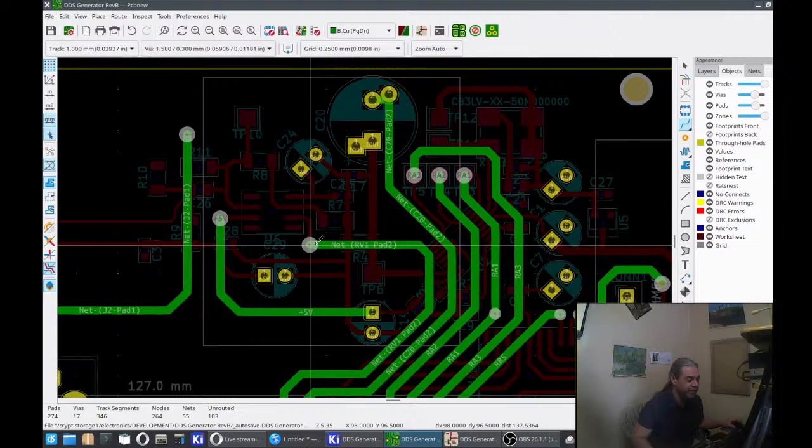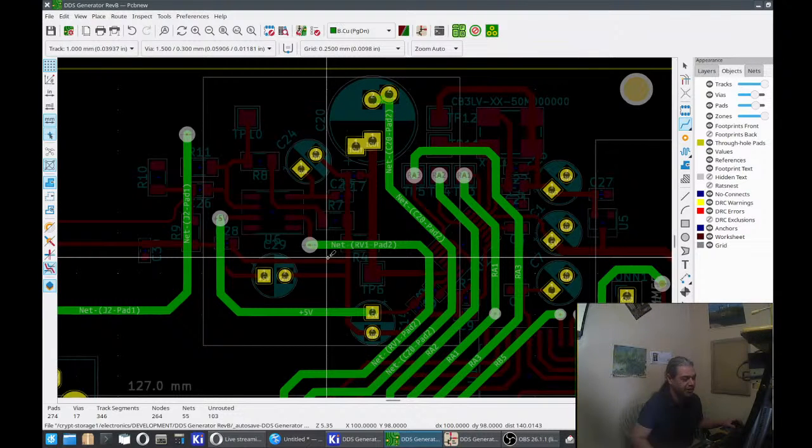So it's whatever you can have in stock, because with those capacitors, you shouldn't have to bend the leads and have the components not seated properly on the board. And by doing that, it allows you to have multiple options, because capacitors at those typical values are so common.